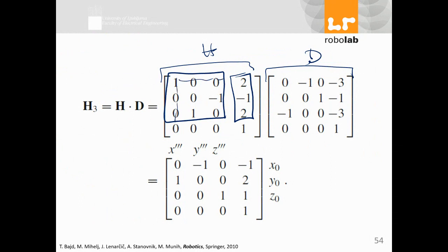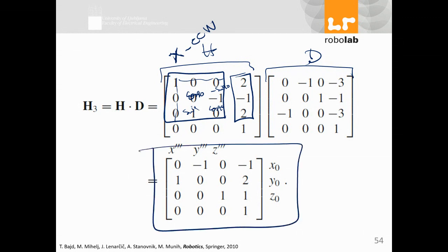You see X is 1. So what you have is cosine, negative sine, with alpha 90 degrees, and that's why you have this value. So it's cosine 90, negative sine 90, sine 90, cosine 90 for rotation around X counterclockwise. Okay, which gives you the final matrix here.